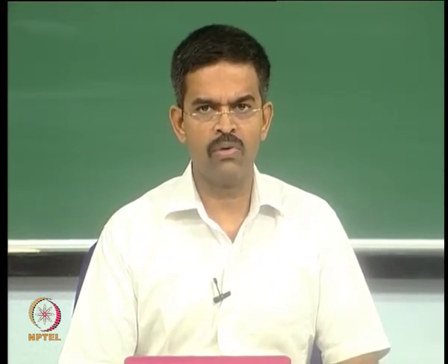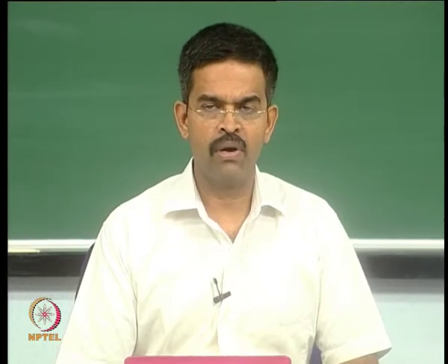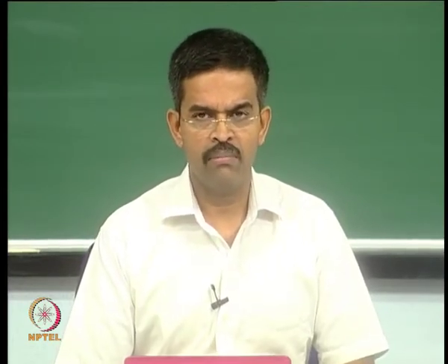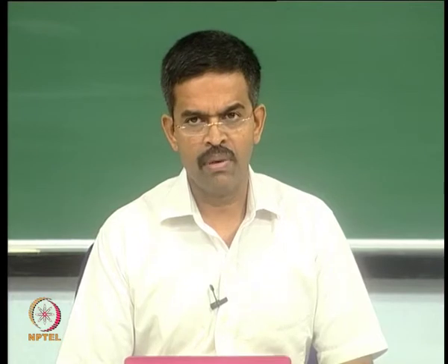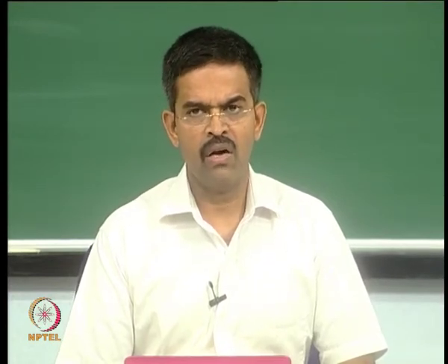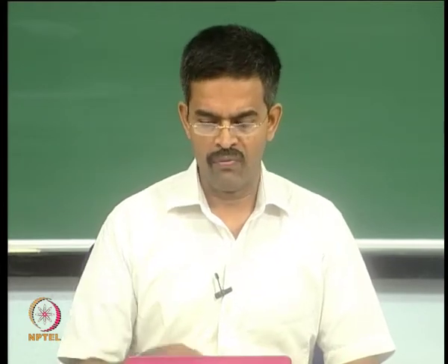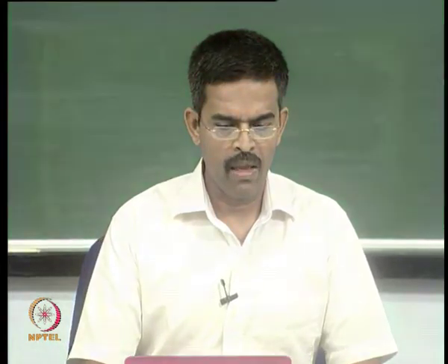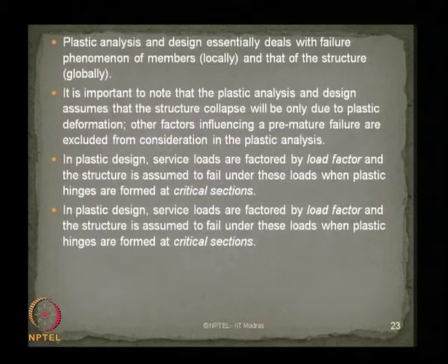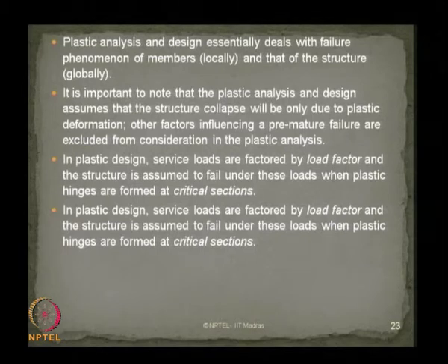Critical sections are not the locations where the bending moments are maximum, they are the locations where a good amount of plastic hinges can be formed because of the geometric variation, because of the load concentration, because of the variation in moment of inertia, or because of the sway mechanism imposed on the structural configuration of the platform. In plastic design, service loads are factored by a load factor and they act at very specific critical sections.